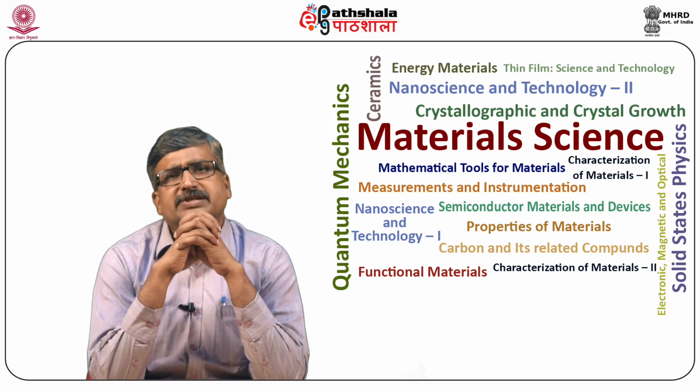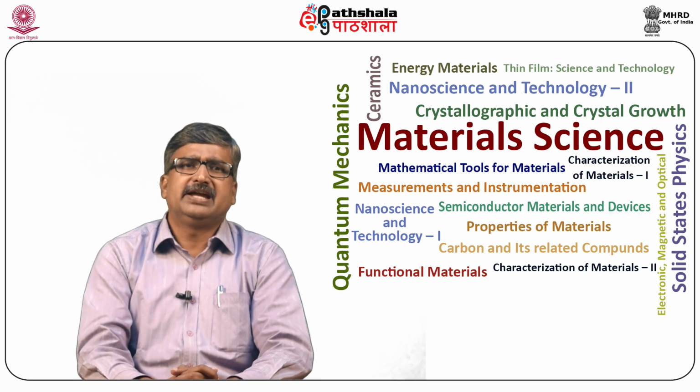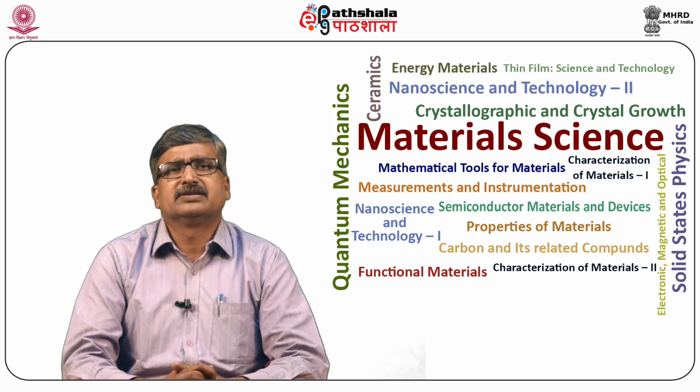This can be accomplished by several methods, which include the sometimes combined use of intrinsic differences in magnetic hysteresis of the ferromagnetic materials, exchange biasing with antiferromagnetic thin films, and antiferromagnetic interlayer coupling across non-magnetic metallic films.